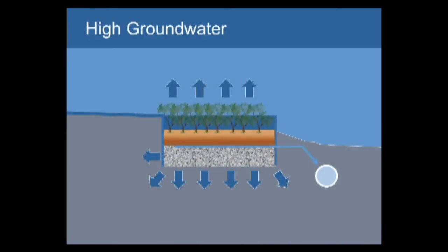High groundwater is another issue. Just pointing out that the PCIs require a minimum 6 inches, and 24 inches is what we're looking for here for the bioretention. As long as your groundwater isn't too close to that, the issue of having a groundwater mound underneath these and potentially not having a lot of distance here really isn't an issue. So if somebody says, oh, I got groundwater within 10 feet or within 7 feet, as long as this isn't extending right down into where you expect the groundwater to be, I wouldn't worry about it. I'd say go ahead and use this. It's still a great solution. You might end up with some less effective infiltration during the wettest periods.